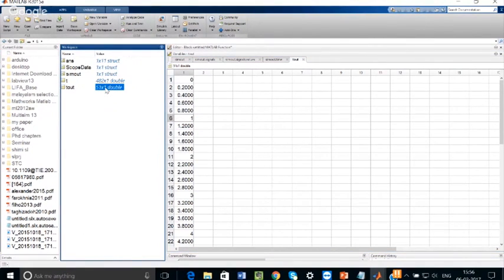So with variable step, whenever there is a change, say in a firing pulse you are giving, at that time what variable step does is go back and check whether the change is perfectly done or not. Okay, there is a perfect change. Fixed step will not do it. So that is about the parameter setting.